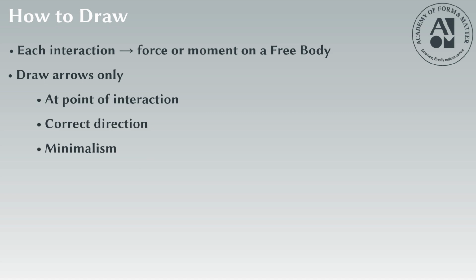Now we draw. Every interaction becomes a force or a moment. Just arrows. No decoration. No architectural ego. This is the one place where minimalism is not a style. It's mandatory. Place each arrow at the point of interaction, in the correct direction. And that's it.